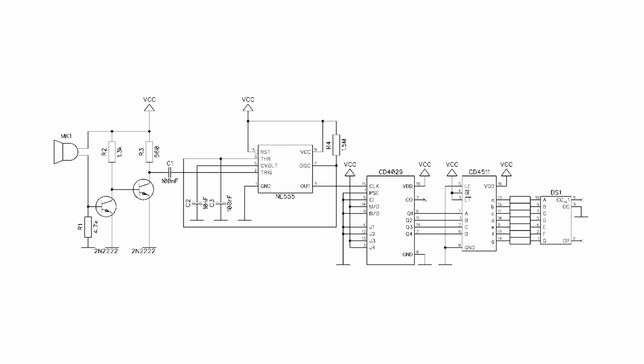A set of 7 resistors is necessary to limit the current of the LEDs in the display. It has a configuration of diodes with a common cathode. This means that we have 7 anodes and they are all connected by a cathode. It should be connected to the ground. In the case of displays with a common anode, we connect it to the power supply and the pins of individual segments are controlled by an inverted signal.